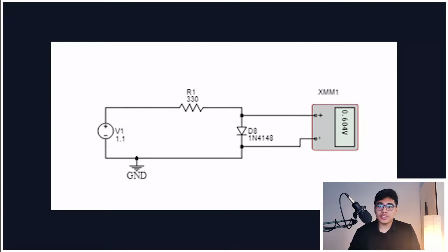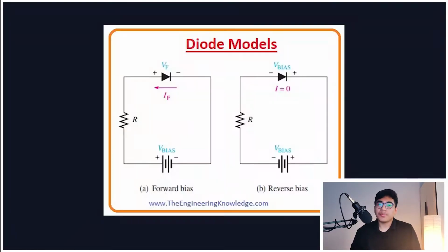As I said earlier in the intro, the diode will work depending on how it's connected with respect to the power source. In A, it is connected in forward bias, while in B, it is in reverse bias. When in forward bias, the depletion layer tends to make there be less resistance, allowing current to flow. Whilst in reverse bias, it thickens, increasing the resistance, making it hard for current to pass through, as in, the current will be blocked by the diode.